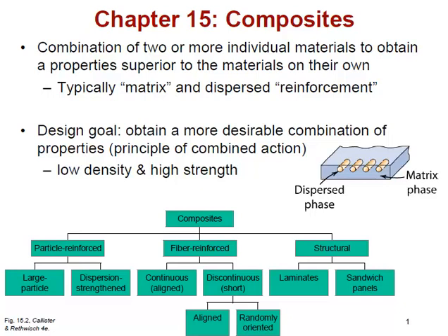But the majority of particle reinforced composites are smaller scale reinforcement, which would be towards the end of dispersion strengthening, like we saw in dispersion strengthened metals for high temperature use. In fact, those are dispersion strengthened composites, albeit spontaneously formed, and they would probably represent the small end of the scale of your dispersion reinforcers.